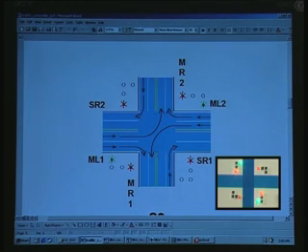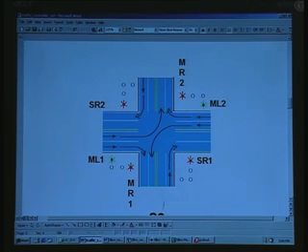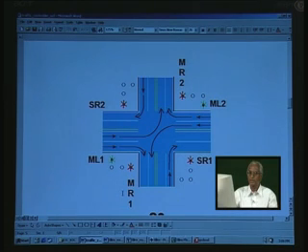the side road. You can't avail it, because first what is allowed is straight flow traffic followed by the left flow traffic for the main road, and all the other things will follow suit, except for the side road. There, the main flow will be 25 seconds and the turn will also be 25 seconds. So you have to take all this into consideration, and then accordingly design the timer and enable them: when to start, when to stop.